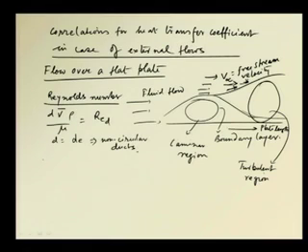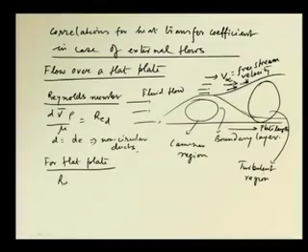So, the Reynolds number for flow over a flat plate, based on this free stream velocity, we can write as Re x, equal to x V infinity rho by mu. Now, we can understand that this x is the distance from the leading edge. So, this is the leading edge, and in this direction is x. So, at any location we get a value of the Reynolds number.